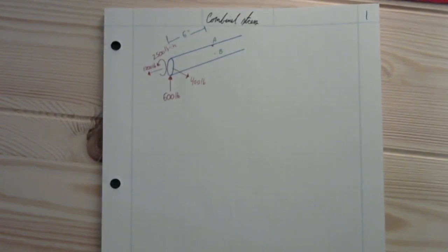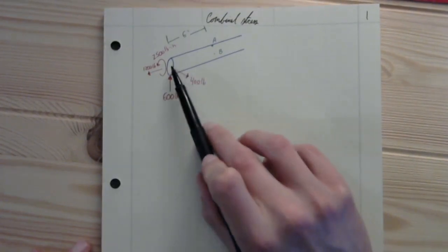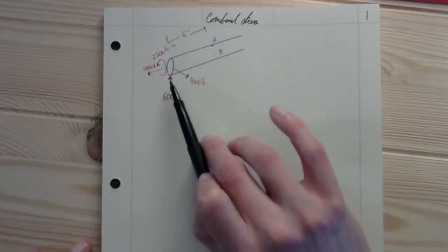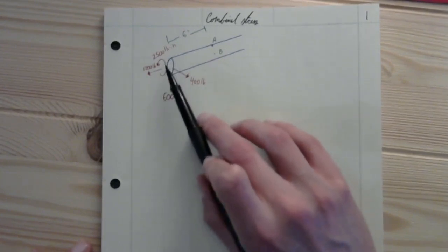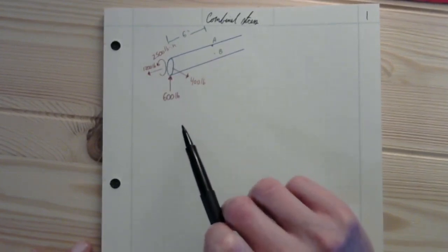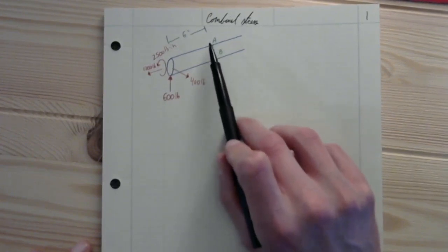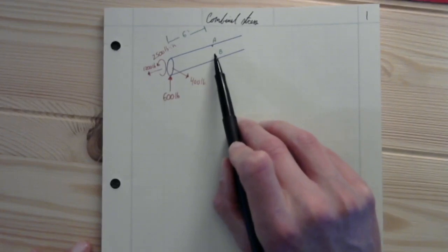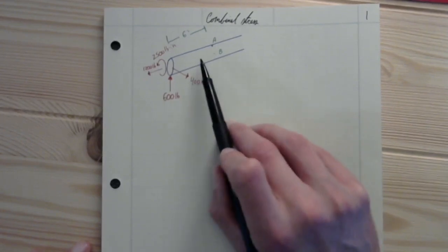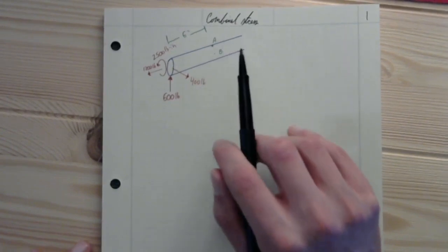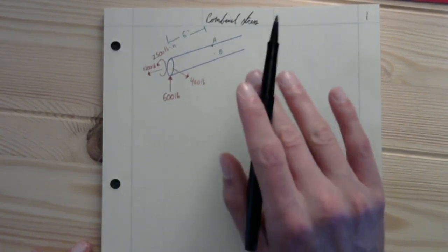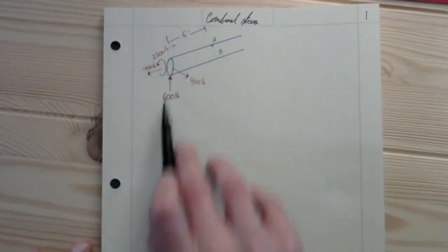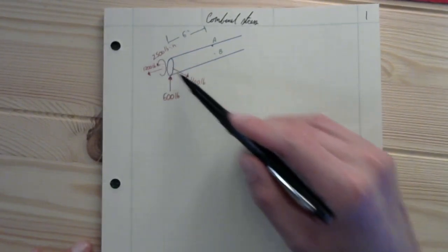We have this example problem to solve, where we have a circular rod that is subject to quite a few loads. And then we have 2 points where we want to know what the stresses are. This one is on the top and this one is on the side, point B. It's a 2-inch diameter bar, and this problem has everything. It has forces in the x direction. We'll call that the x direction, this the y direction, and this the z direction.